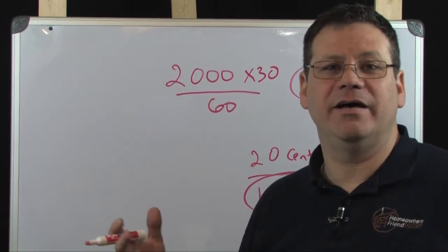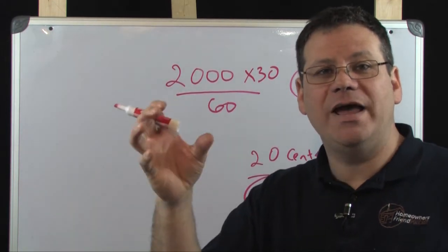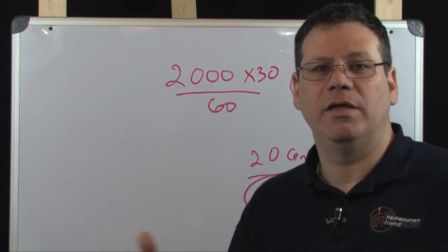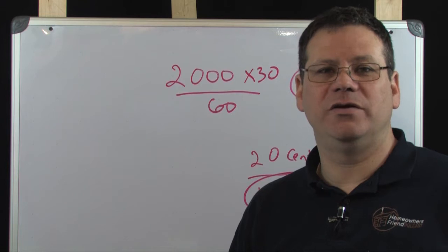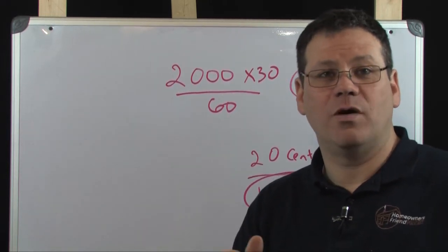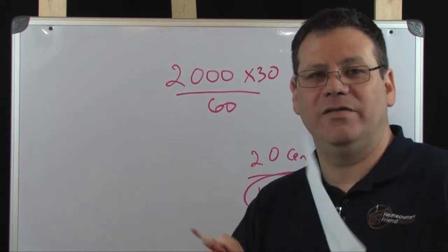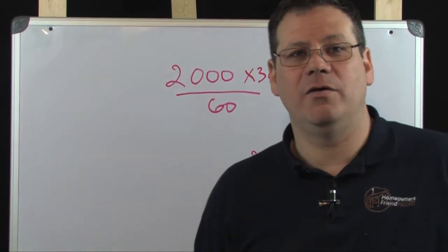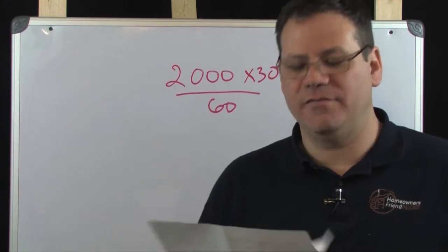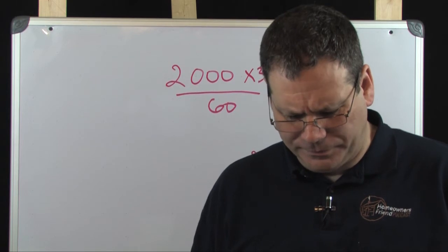And it's like one of these compact fluorescent light bulbs. It's giving you the light, or in the case of the microwave, the heat in the food. It's warming the food up, but it's not warming the air up. It's not warming up the appliance. When you turn your oven on, you've got to warm the appliance up, the air up, and then the air in return warms the food up. With the microwave, you're just sending the microwave energy into the food, and that's what's heating it up. And it's not really heating up the air of the oven at all itself. I mean, it does warm up after a while because the food gets hot within the oven, and that heats it up. But it's a lot more efficient. So that's kind of cool to know.